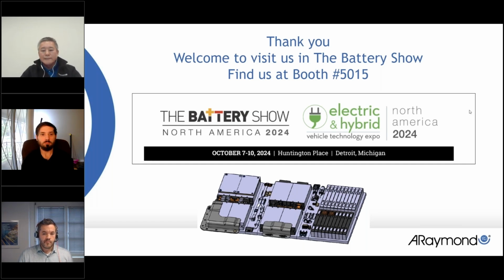Maybe that's why we are seeing battery packs burning down. Sometimes it's not because of your cell, it's because of the connection. And the connection is usually a huge bottleneck for overall resistance. The other way they can do it is to just weld it down, right? If you weld well, it gives you really low resistance. However, thermal expansion and vibration will affect your joint integrity. For the long term, it's still a risk. And it's not easy to repair or service.